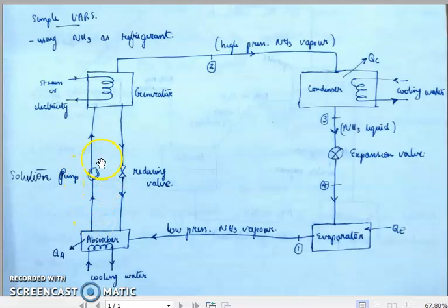Here, instead of a dedicated compressor, just like we discussed in module 2, we are not using any compressor for increasing the pressure of the refrigerant, but we are using a simple hydraulic pump, or solution pump, which will be pumping the water medium which is rich in ammonia refrigerant, pressurizing that water containing ammonia towards this generator.